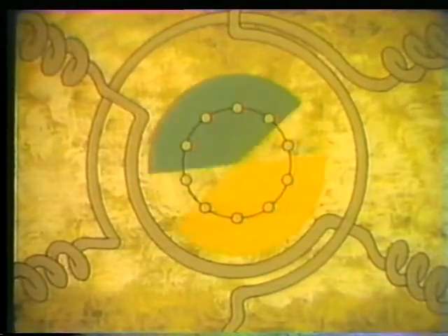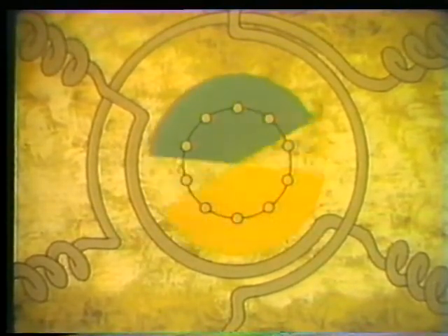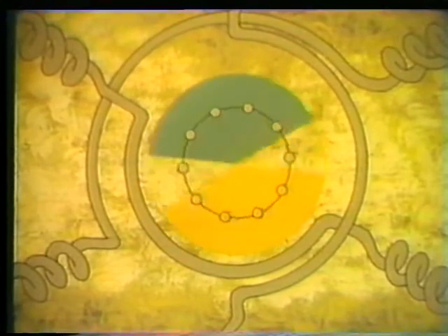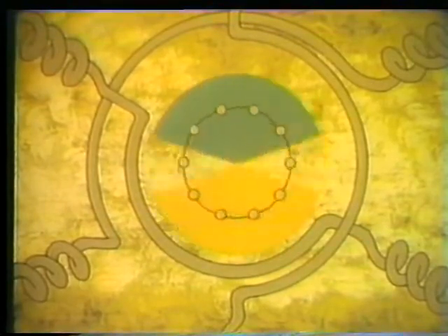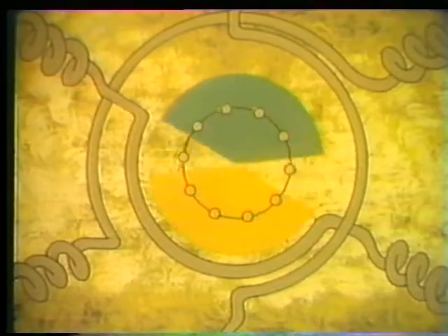Now, this effective voltage is greatest when the motor is first started. At motor start, the stator's magnetic field is rotating at high speed, but the rotor is just beginning to turn. The difference between the speed of the rotor and the speed of the stator's field is maximum, and the voltage induced in the stator is also maximum. Therefore, current flow is very high at motor start. In fact, in a typical AC motor, starting current is 3 to 5 times higher than the normal running current of the motor.